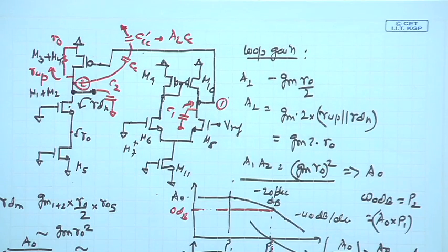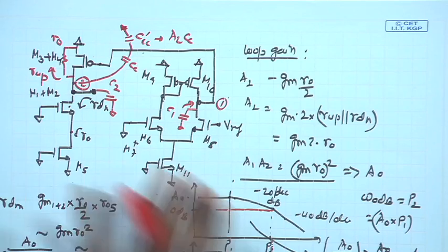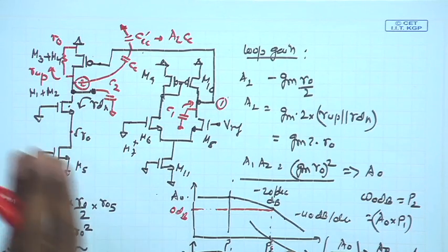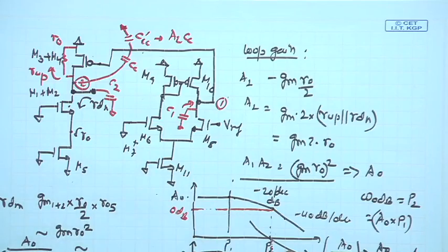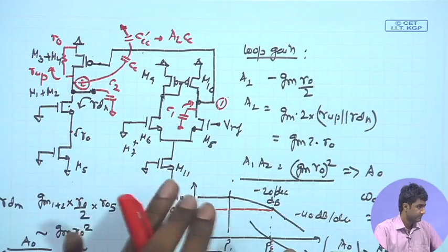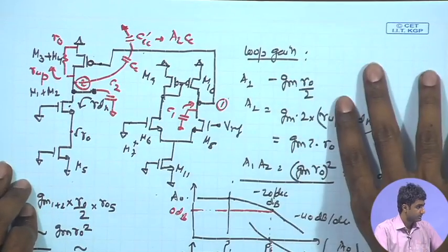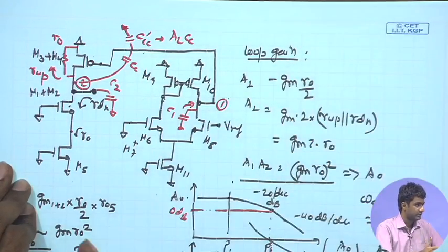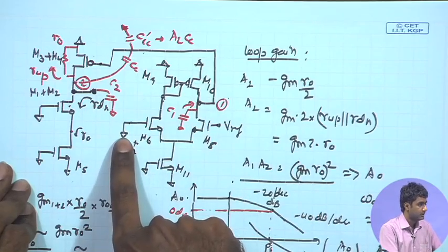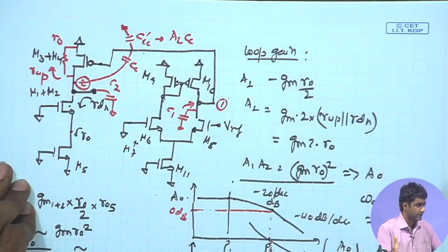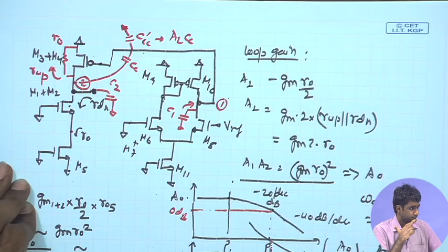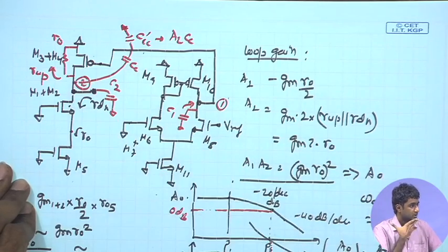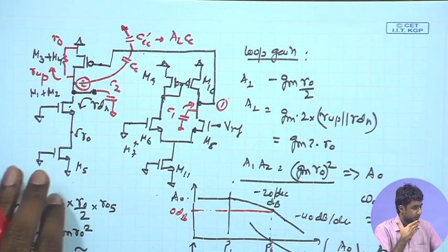So, why are we choosing 45 degrees as phase margin? 45 degrees is a safe phase margin for which, in the overall transient response, you do not get much ringing. If the phase margin is lower than 45 degrees, time domain analysis shows that it will lead to ringing in the closed loop response. If you put a step input in the loop, it will give you a ringing response at the output. Then why aren't we choosing 60 degrees, which is even better? The design becomes more challenging, compensation becomes more challenging. So, 45 degrees is an acceptable number.